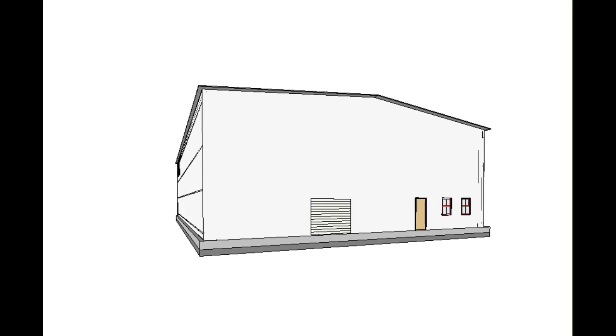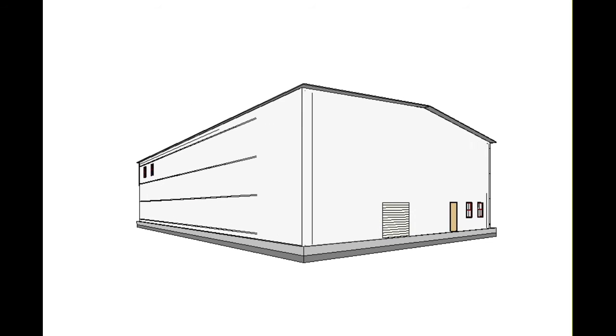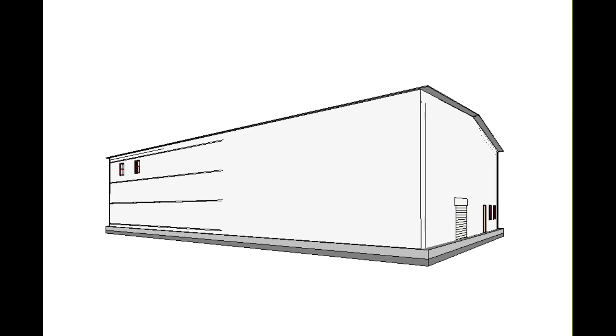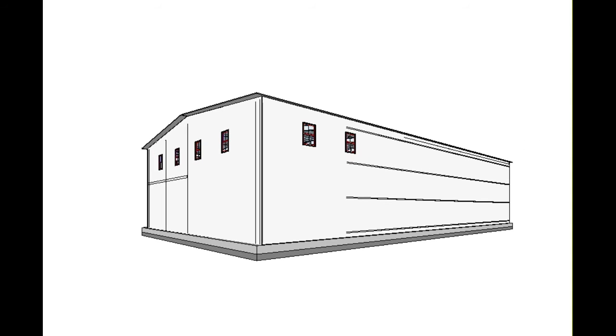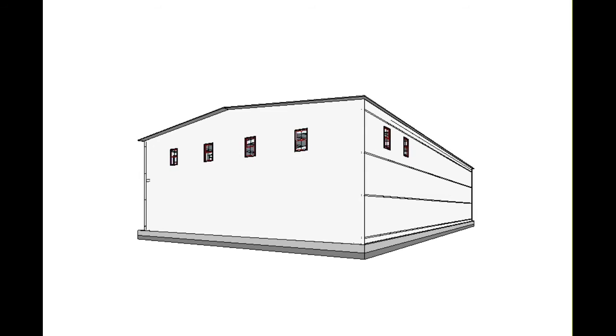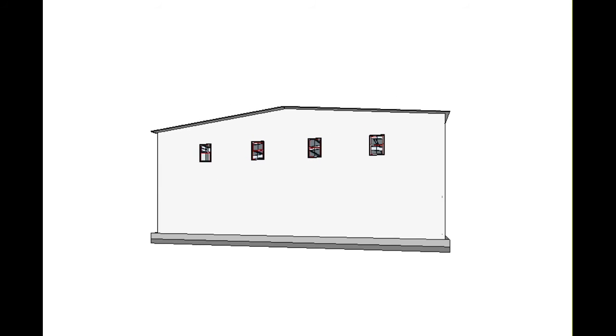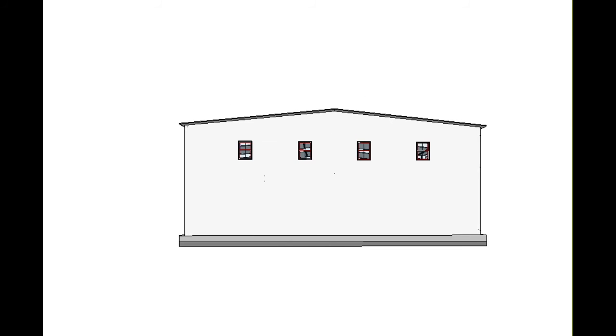In the design, the spacing of the columns is 5.33 meters apart, making it sit within the client's specifications and also giving it the strength and rigidity required to handle the crosswind and forces that will be experienced by the structure. On the eastern facing, there are 2 windows and a standard sized door, as well as a roller door.